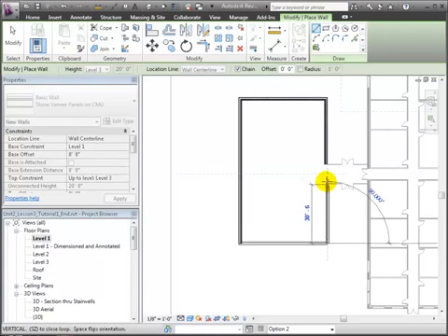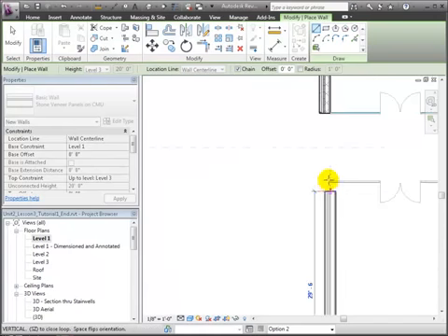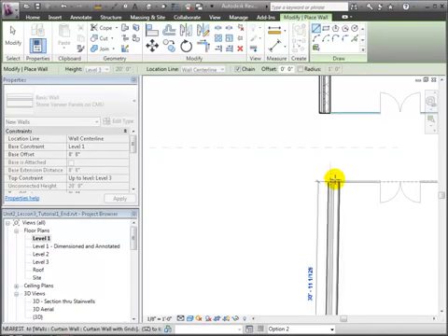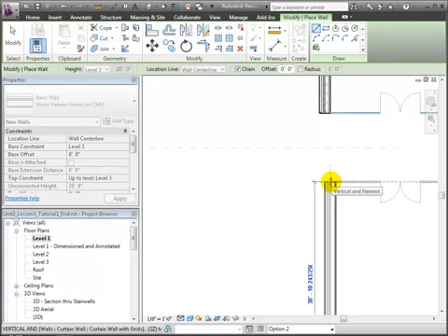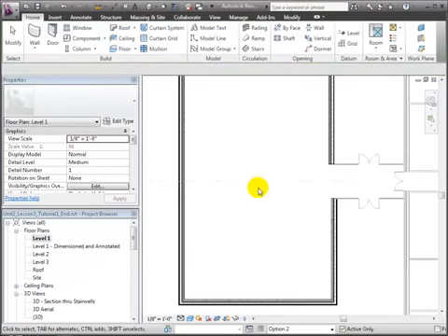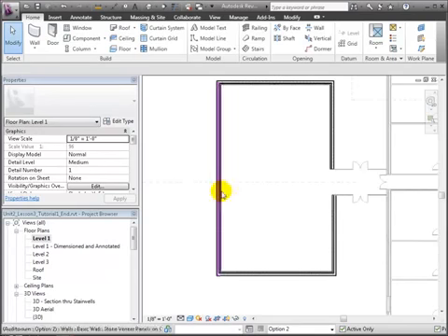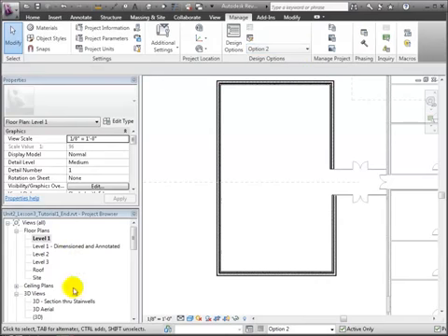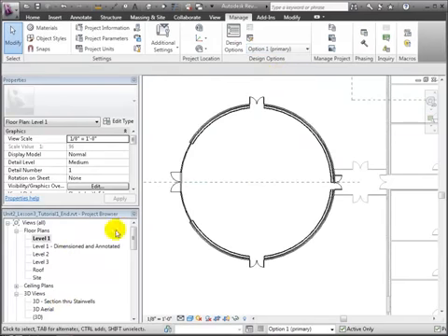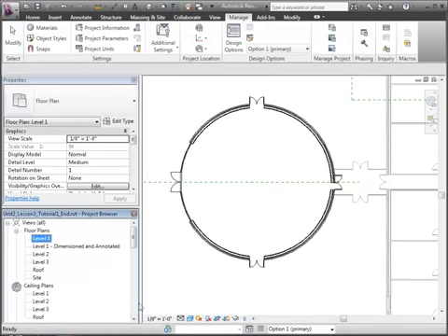And we can easily toggle between the options in the main model from this drop-down menu. Remember that the main model by default displays the primary option, so be mindful of which option you have set as the primary option, as this will be the one that by default appears in your model views unless otherwise specified.